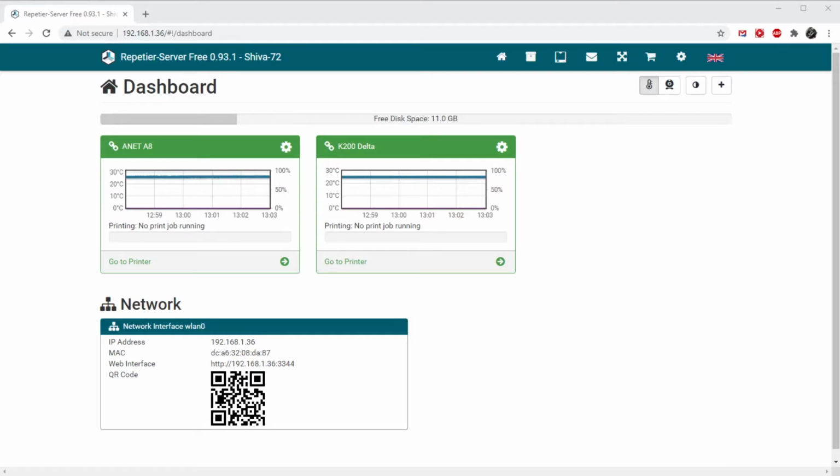At this point, there are many different ways you can get your data to the 3D printer. You can plug the micro SD card into an appropriate reader and copy the file directly to the micro SD, then physically transport the micro SD into the operating board of the 3D printer, most of which have a little micro SD reader, and then use the buttons on the 3D printer to navigate through the different submenus and to load the file and press print.